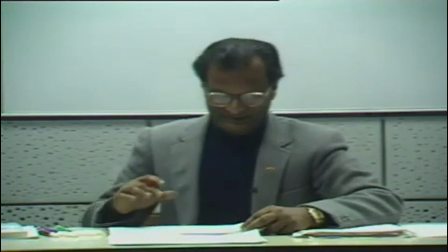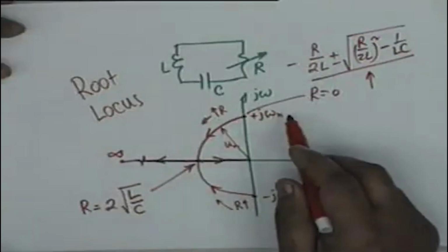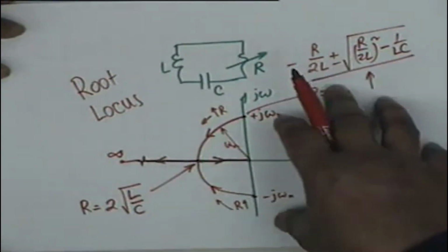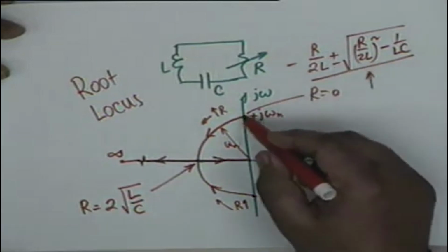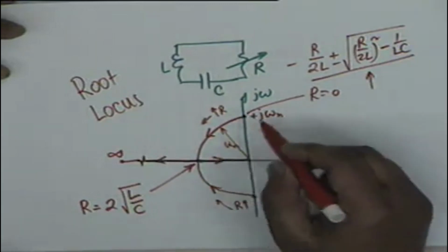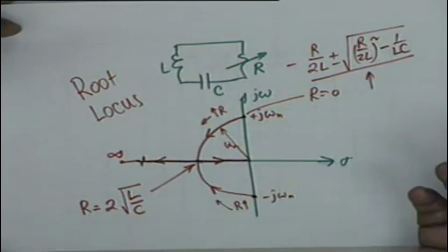as you shall see later, if you are a mechanical engineer, in control systems, in any process control, for example, which can be modeled as a second order or third order or fourth order system, suppose one of the roots, due to a disturbance in a parameter, goes to the right half plane. If the root locus includes the right half plane, what will happen? Or the imaginary axis, then what will happen? Suppose the parameter is such that the roots are on the imaginary axis. Then the instrument or the process that you are experimenting with will never settle down. It will go on oscillating.